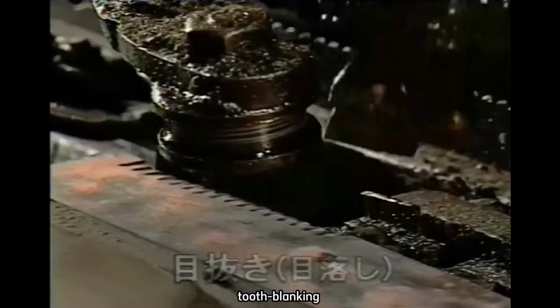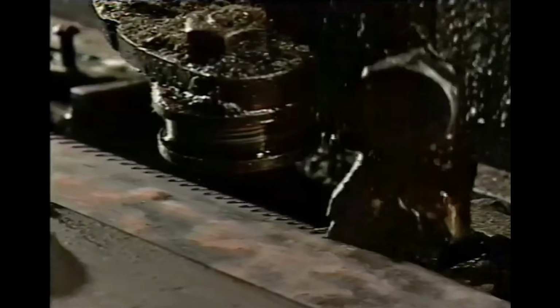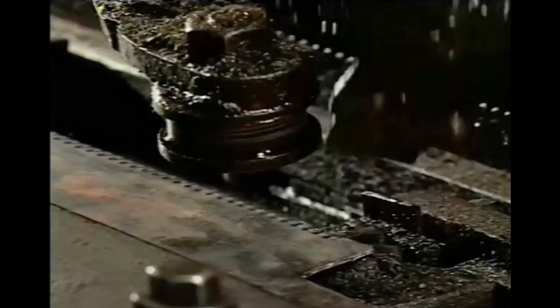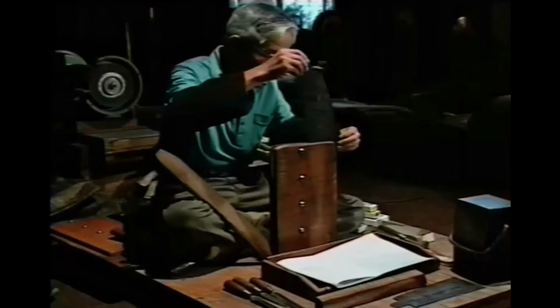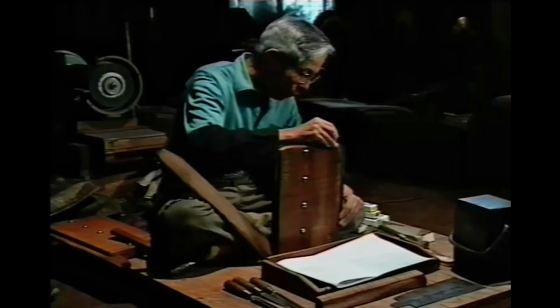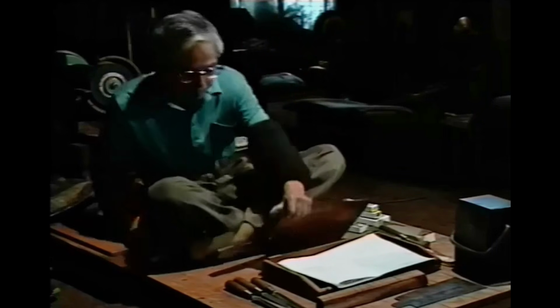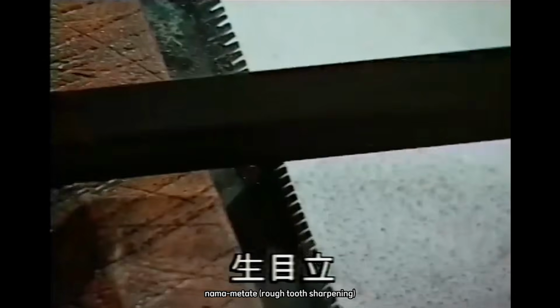Each tooth of the saw is knocked down individually with a steel tool. This is called tooth blanking. Both rip teeth and cross-cut teeth are tooth blanked in turn. Before hardening, the blade is clamped in a tool called a nokobosami, and the first tooth setting, called nama metate, or rough tooth sharpening, is performed.